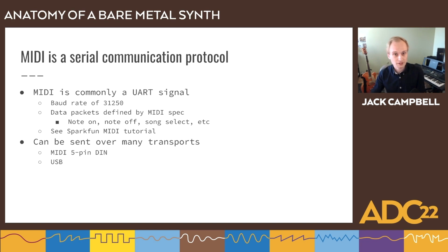We're using 5-pin MIDI DIN, but you'll often see MIDI sent over USB. USB MIDI controllers are quite ubiquitous. You'll also see, I don't have any Bluetooth MIDI devices, but I've heard that that's a popular thing that's coming up, and it's pretty nifty. You'll also see it over TRS, just like the little 3.5 millimeter audio jack type plugs. I believe that is becoming popular in modular, though I am not yet in the modular boat, so I don't really know how true that is. But for what it's worth, Daisy's preferred mode, it seems on its website, is to send MIDI over TRS.